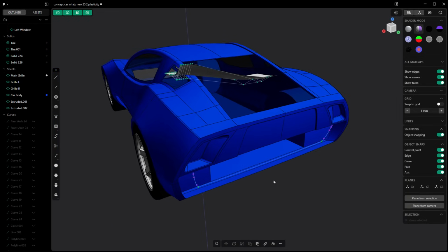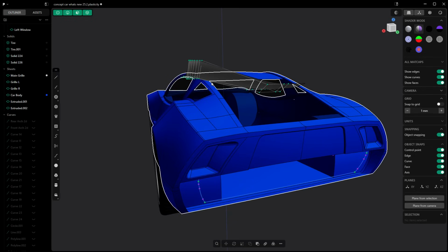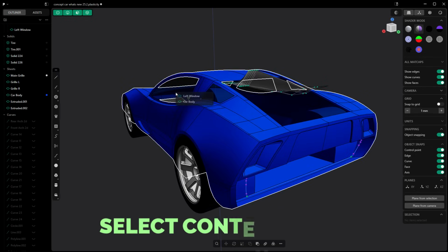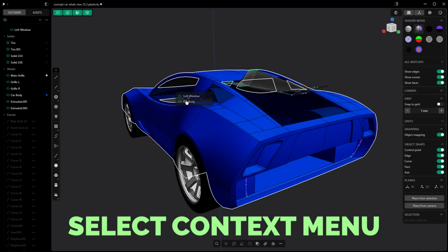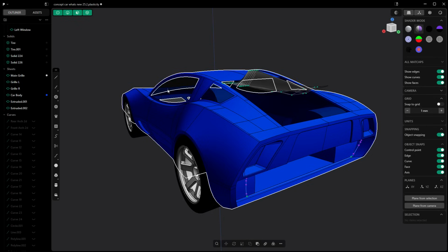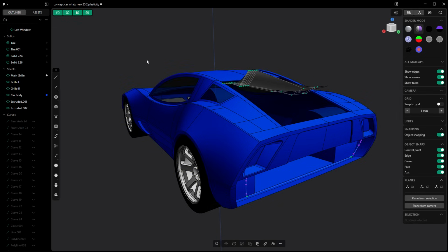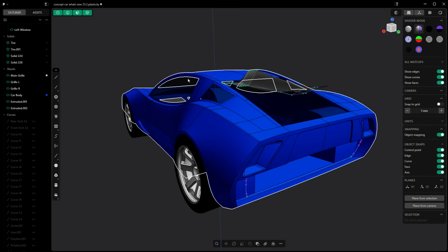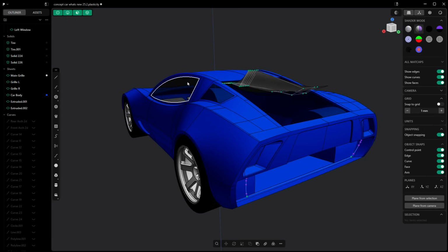While we're talking about selections, something that we've been able to do in Plasticity for a while is hold down the left mouse button and then roll through the mouse wheel and get a list of the objects that are underneath the cursor. Now, the problem with this is if you move the cursor at all and start to create a selection dialog, it doesn't work. And for me personally, I've never used it because I generally use my pointer finger on the mouse wheel and on the left mouse button, so it's never felt real comfortable to me.